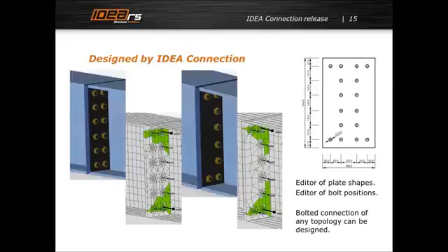How can I see that in the graphical overviews, or is it at least possible to tell the software, I want you to place the shear force on, say, the lowest row of bolts, because that's the distribution I, as a designer, have in mind when making my hand calculation.